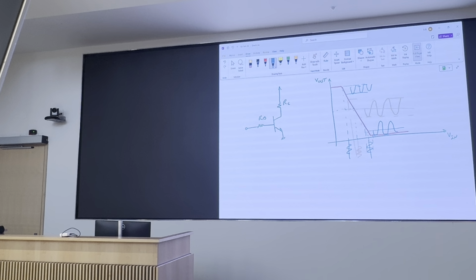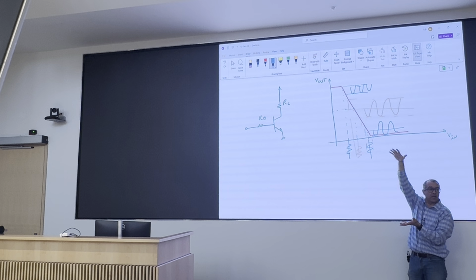So how do I do that? I choose the right VCE value for the expected output amplitude. If I know my amplitude at the output, if it is the output stage of a speaker, an audio system, let's say a 10-volt supply, I want to deliver the maximum power to this poor soul. I want to use all of that 10-volt range, right? So I put my bias point exactly in the middle of that range. So I have the largest signal at the output without distortion.